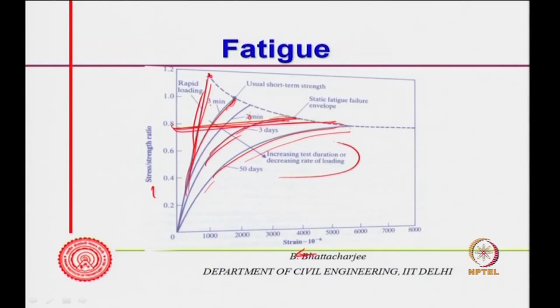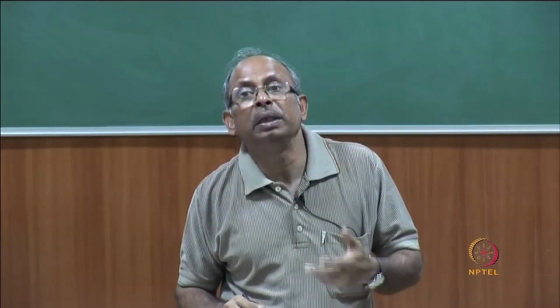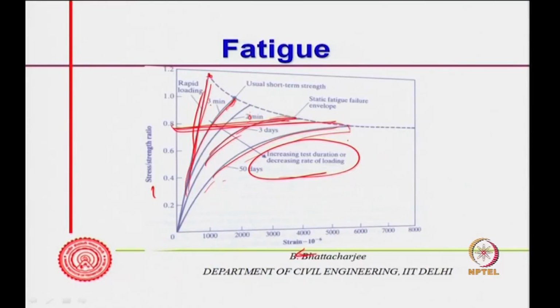Increasing the test duration means that I am decreasing my rate of loading, and at a lower rate of loading we have seen that it fails earlier. So, the same load applied over 50 days, you find that the load carrying capacity is much less. So, I can actually have a kind of envelope.